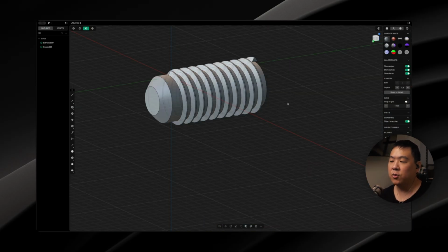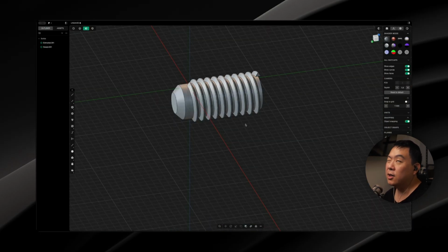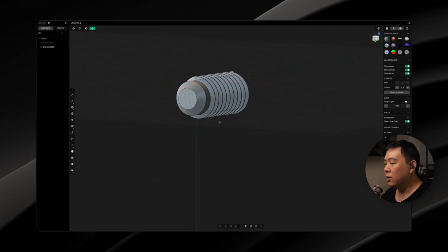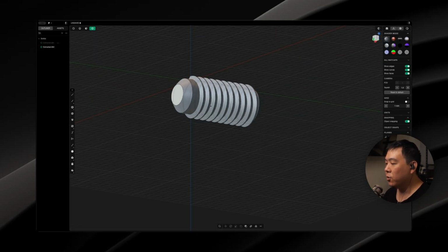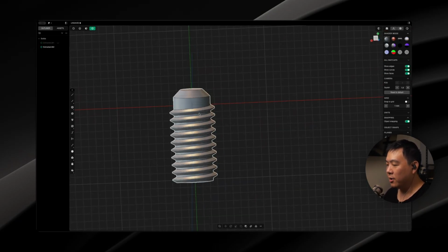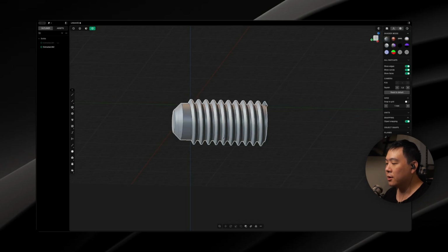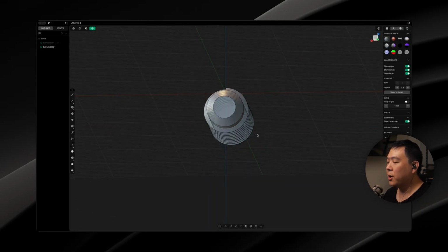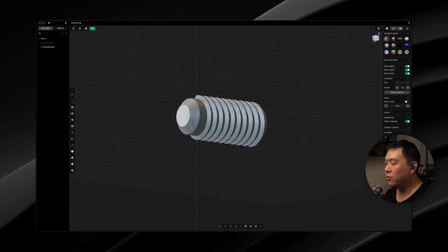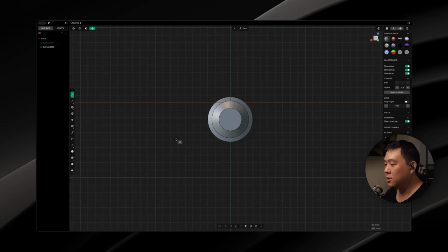And that'll make these threads a little bit thinner. One last trick before moving on to, I guess, the nut. You can ask yourself whether or not you actually need a cylindrical profile. If I Boolean this together, in order to make it stronger, because right now, if you were to print it, you would have to print outwards, and these threads will go along the layer lines, which is a little bit weak. So ideally, you want to print it flat like this, but of course, it's hard to print these without supports. But if you don't need a cylindrical profile, you could just take a line and cut off part of it, and this would still work, right?